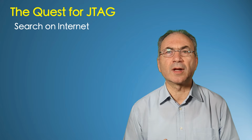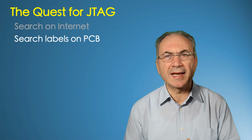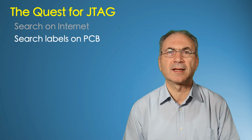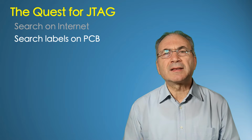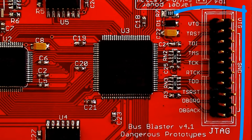We can start looking at the board, searching for pins labeled with the names of the JTAG interface like TCK, TDI, TDO and TMS. But in our sample router board, we weren't able to find these labels. But in a few boards, like for example the one shown here, we are able to find these labels, and so the job is quite easy.